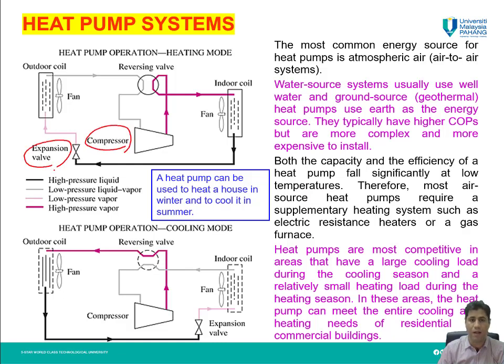We have an expansion valve, but here instead of the evaporator and condenser, we call them coils, which we have an indoor coil, which we can say is an evaporator, and an outdoor coil. As you can see here, we again have a cycle from the expansion valve to the outdoor coil, then to the indoor coil, then to the compressor, and this cycle will continue with the same components, similar to the refrigerator.